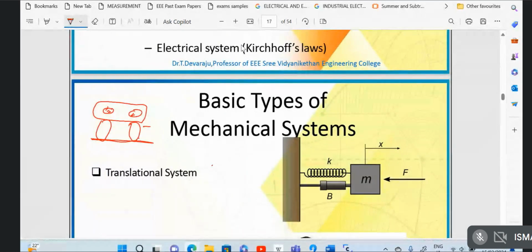Sometimes the wheels also have springs. The vehicle also has springs of its own. Then there's a shock absorber in line with the springs. Otherwise, without the shock absorber, the vehicle will be vibrating forever.